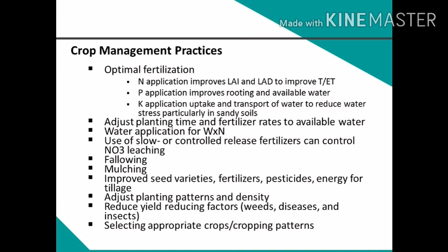There are some limitations when we use the term water use efficiency as well. For example, some researchers have pointed out that water use efficiency is actually an index and not an efficiency because there is a theoretical limit for yield. And the typical term water use efficiency, which relates yield to transpiration or evapotranspiration, does not include all the agricultural benefits like economic or social or environmental benefits such as groundwater recharge.